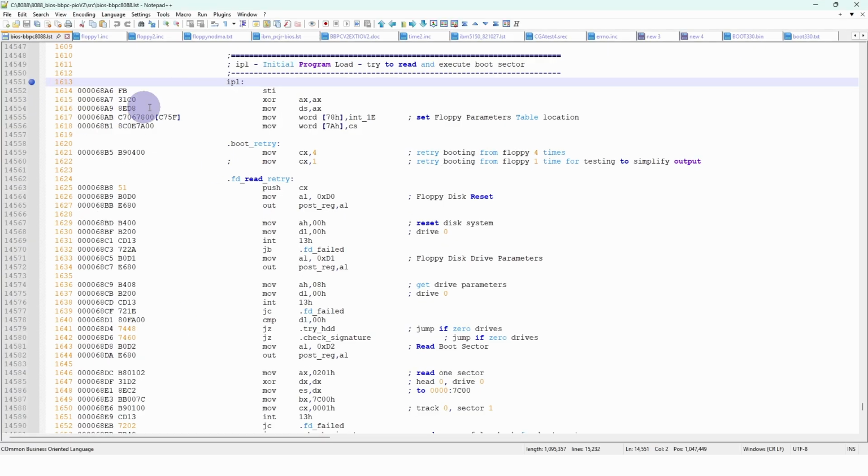So this is the IPL code in the XI8088 BIOS, and you can see here that we do floppy disk resets. There are some power on self-test codes you'll see here. In the power on self-test port output that I record, a lot of these D0, D1, D2 come from the debug information that I've put into the startup code here.